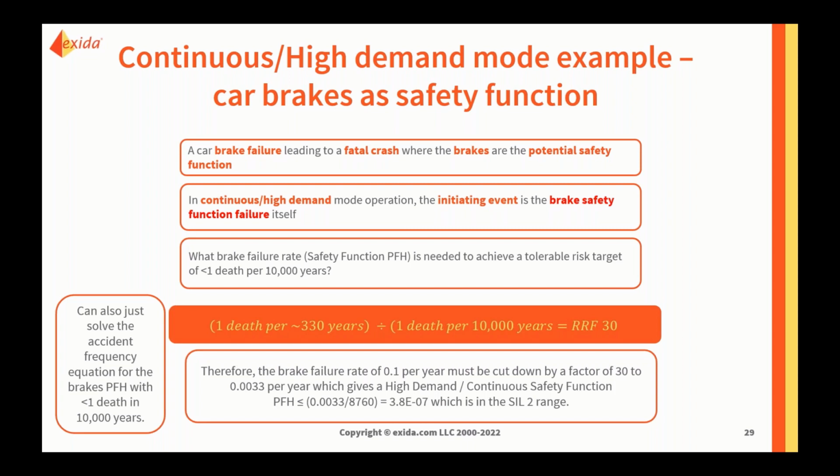So here we have used LOPA to identify a SIL target for our high demand brake function of a PFH of less than 3.8 times 10 to the minus 7 and at least a SIL2 overall integrity level in this.